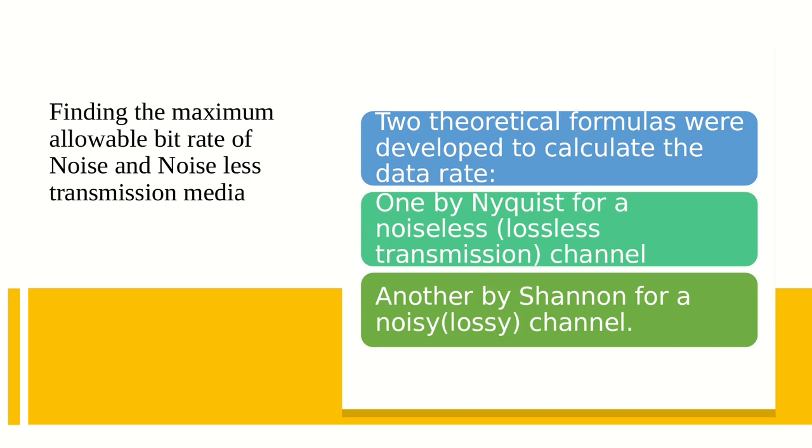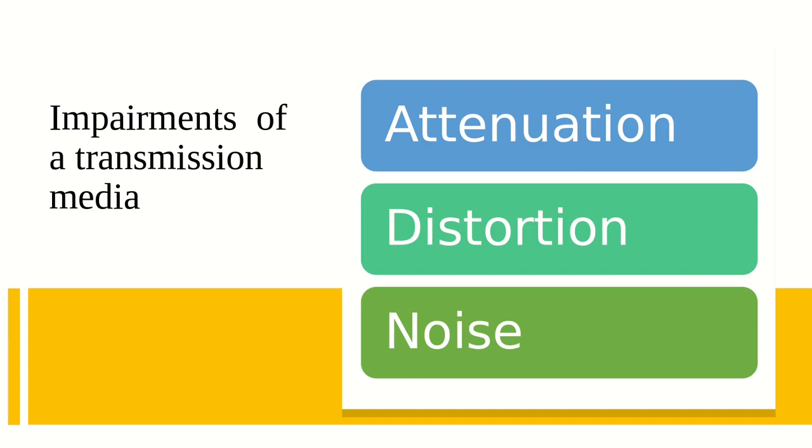How can we find this bit rate? If we need to send bits faster, we need more bandwidth. For a noiseless channel, the Nyquist bitrate formula defines the theoretical maximum bitrate, or how many signal levels we need. For a noisy channel, we need to use the Shannon capacity to find the maximum bitrate, or the upper limit.